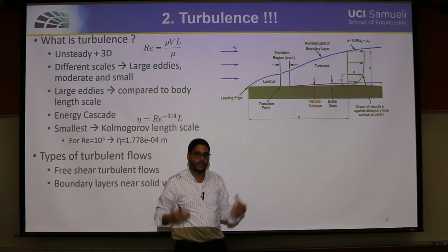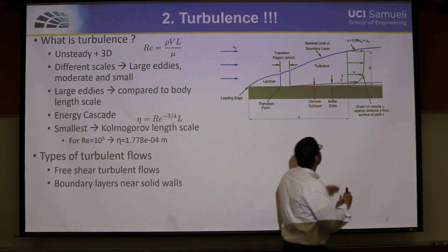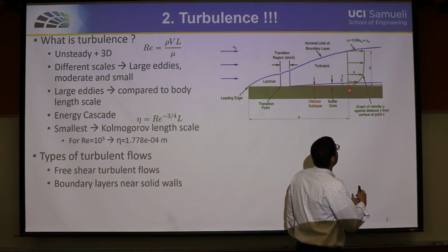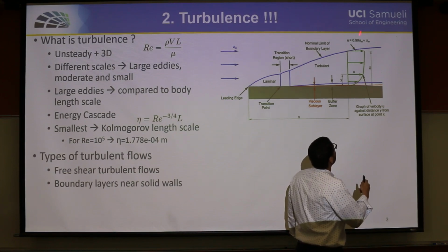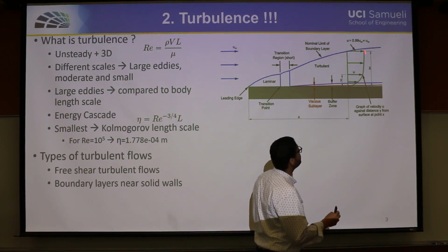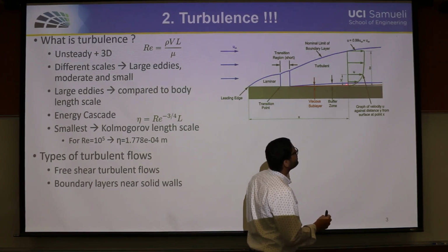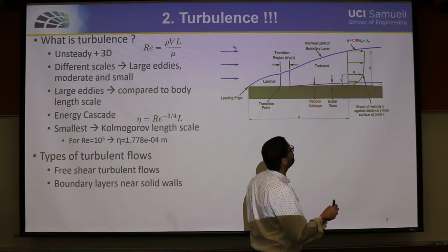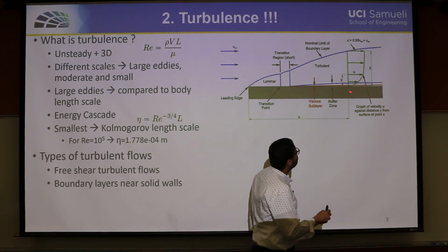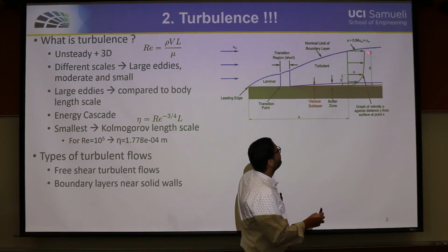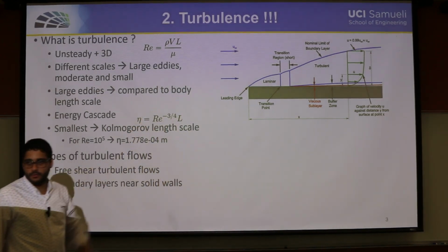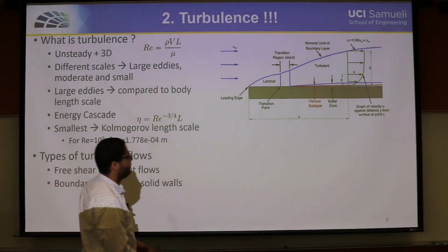You will get a discontinuity. That's not physical. So what nature does is that it tries to smooth your velocity profile from a 0 value on the wall up to the maximum value that it can reach up there, and it gets a kind of smooth shape. But you can see that this transition between a 0 value and U infinity possesses an exponential behavior. It happens very fast with a very steep gradient near the wall, but the gradient becomes lower and lower as you reach the free stream or the maximum velocity.